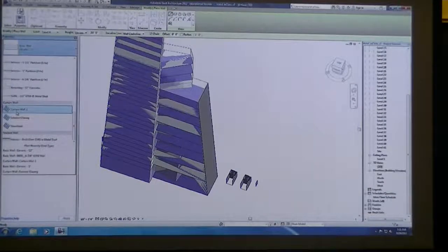Revit treats curtain wall and storefront systems in a different way. Storefront systems in Revit give you an equal spacing of grids. Okay, it gives you these options to say, you know what, no matter how big my wall is, I want 5 equal spaces, and I get this nice grid of 5 equal spaces in the horizontal, and I could change to the vertical and make it 8 equal spaces. Everything gets pinned, everything gets locked and is determined by those parameters, and you don't have a lot of flexibility in changing the design because you're just going to assume you're going to have a grid system.